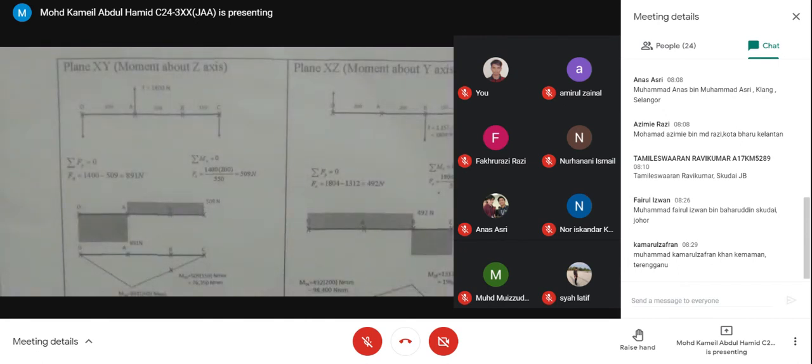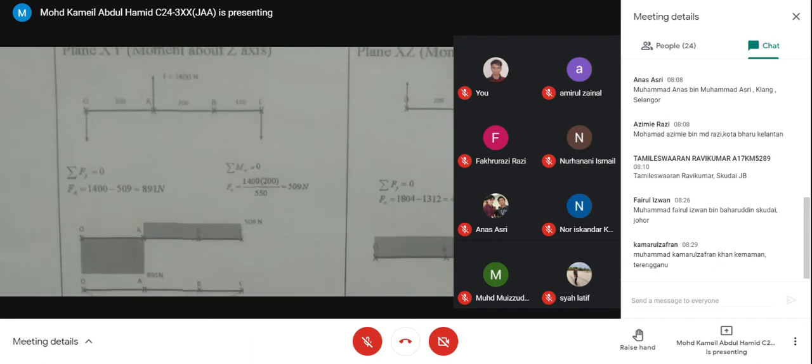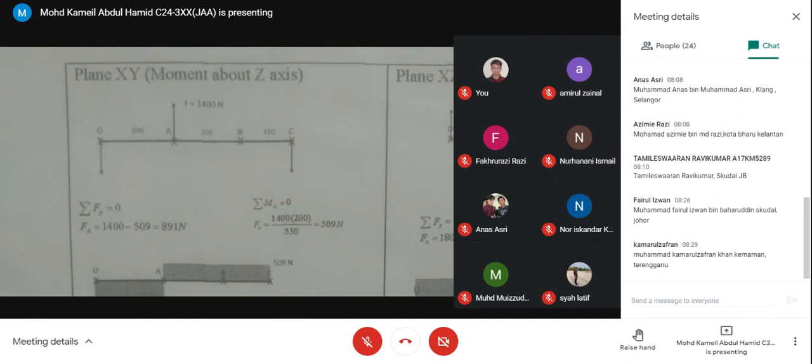Point B, the pulley, from this view. Then you have your support at the bearing. The support at bearing O can point downward. Support at bearing C can also point downward. So just calculate taking moment, taking moment, solve for FC or RC, and then summation of vertical.